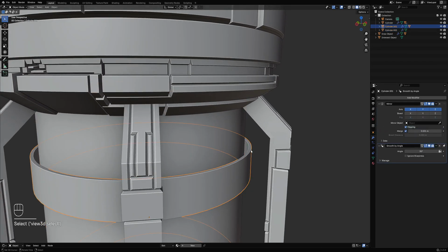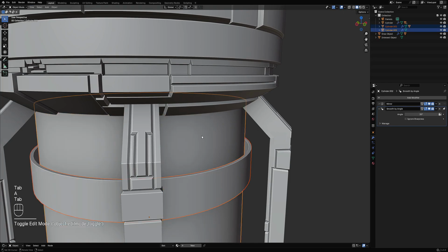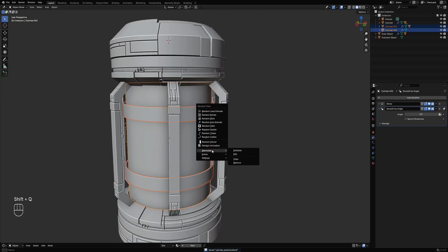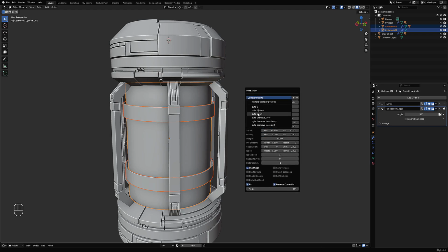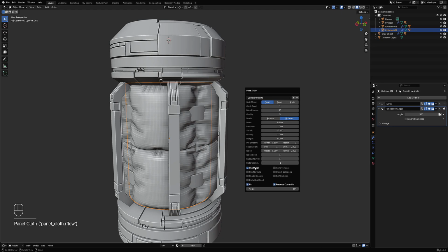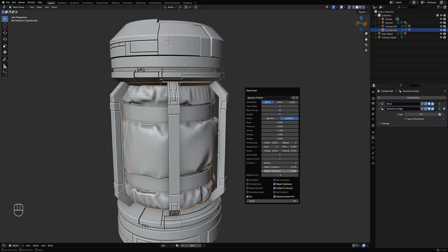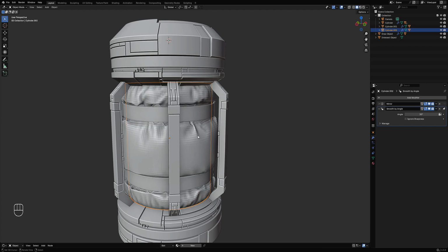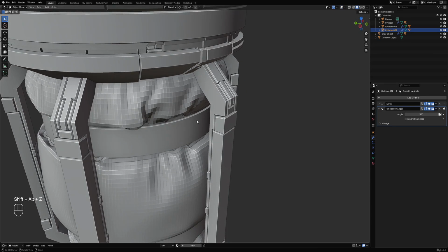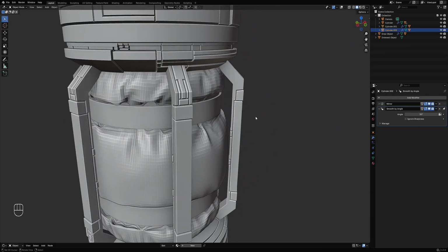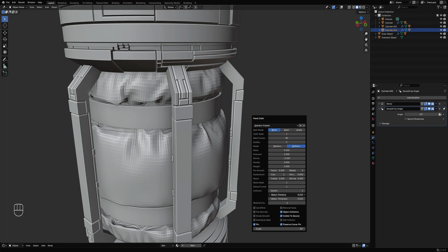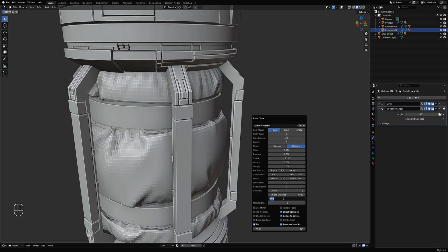Selecting this part and then this part that we're going to turn into cloth, and then extras, utility, panel cloth, buff. Don't use mirror, and object collisions. Okay, and there is gravity, turn the gravity off. Okay, so we have collision with these objects here. Maybe I shouldn't have deleted the back faces. Probably it needed them for the collision, but 0.01 and 0.01 hill as well.